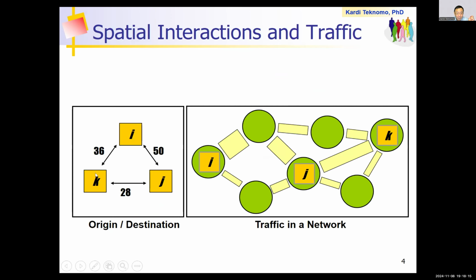Remember, from each OD, origin destination, you know the trips by mode already. And then you convert everything into PCU per hour, not by mode, but now into PCU per hour. Now you have trips from I to J, J to K, and so on. And when you put that demand by zone, this one is still in zones, right? So now you put it into the actual links and nodes on the road network. That is traffic assignment.